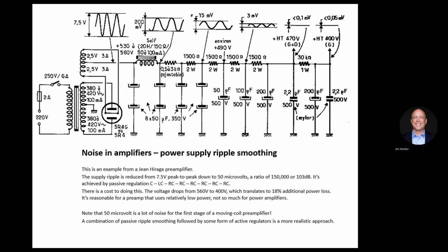No. And this picture shows why. Because if you put a big capacitor here, you're not going to get a lot of this voltage swing, or hum level. So he put several levels of resistor-capacitor, and each one of them knocks down the hum level.